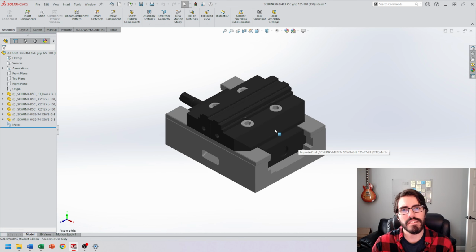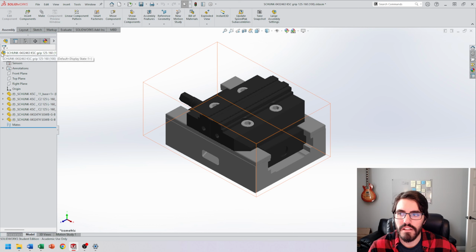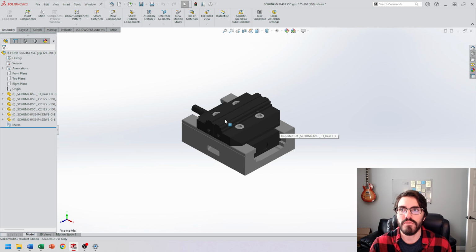And you'll notice that this is a little different than the first part that we were referencing, that riser. So instead of it just being one body, it's actually an assembly. You can tell that by that little icon, the little yellow Tetris piece with the blue square, with all these other different components or parts that are embedded into this dumb solid itself. And this is helpful because if you want to export an assembly the way that you're seeing it, you can do that. You can just make it a Parasolid or a STEP file and then include all those components in one file. Especially if you had an assembly with like 100 different components, you could just flatten it into that one file with this STEP export.